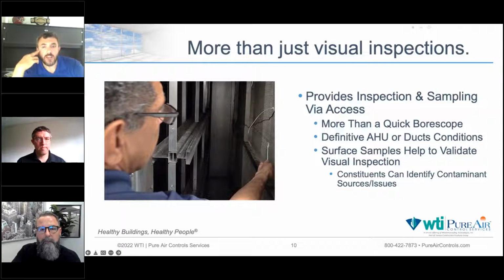A classic example is you take an RPM measurement and it's running below design, and you might want to make a change to the sheave size, especially if you're struggling to get air changes downstream. If you're trying to achieve certain air changes, you may not realize you have more capacity in that air handler until you do some simple measurements with a tachometer.